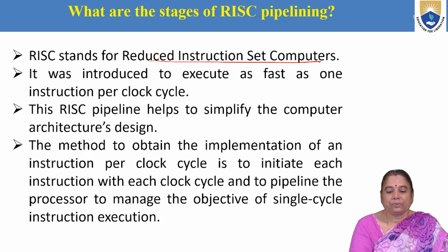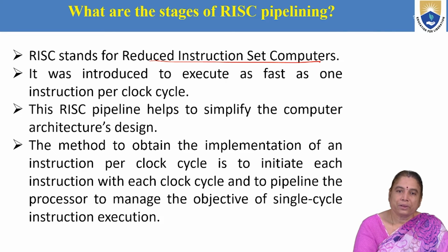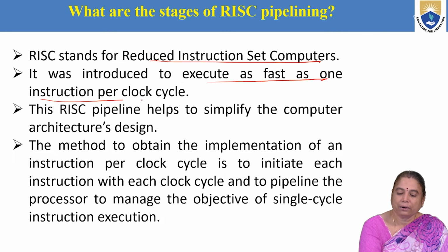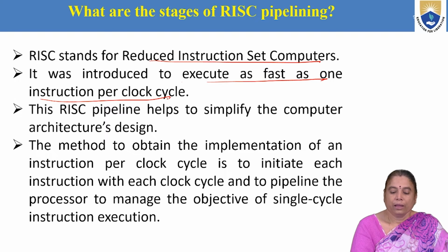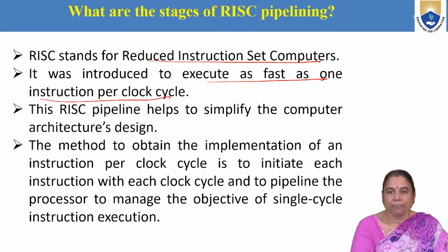These instructions can be reduced and optimized in the RISC architecture. RISC was introduced to execute as fast as 1 instruction per clock cycle. And RISC pipeline helps to simplify computer architecture design. Why? Because it is a reduced instruction set. A few number of instructions are available.